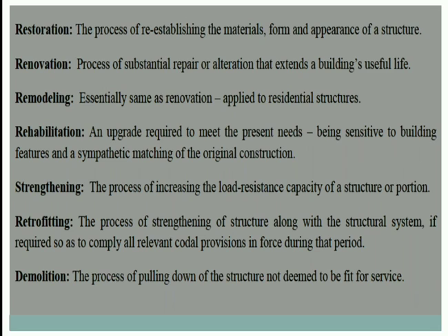Renovation then. This word we have most commonly used because houses are renovated quite frequently these days. It's a process of substantial repair or alteration that extends a building's useful life. In case of renovation, the client's requirements are also given a weightage. Many times there is an extension of the building for fulfilling the space requirement. Secondly, renovation is done with respect to aesthetics. So renovation is a process where we are again altering the interiors, especially the inner walls and all. Here generally we don't touch the structural components.